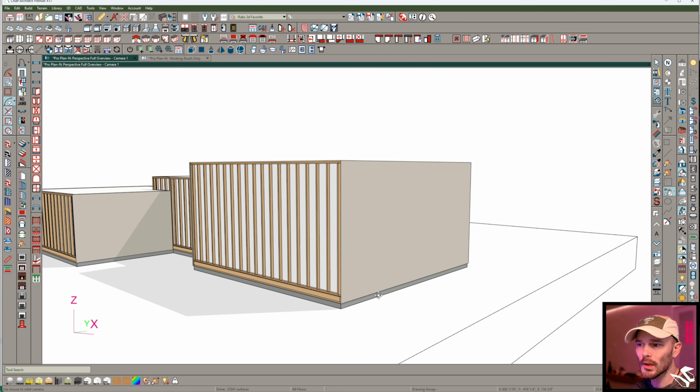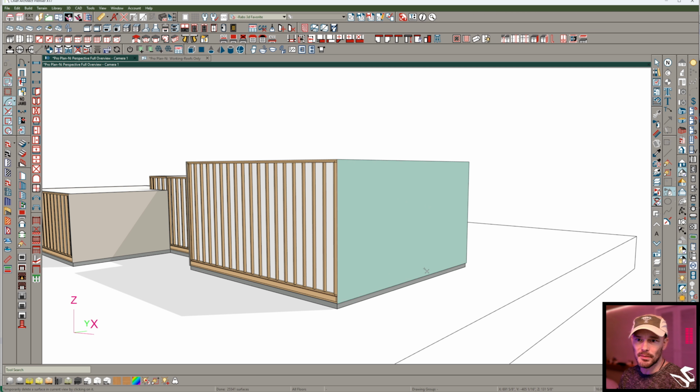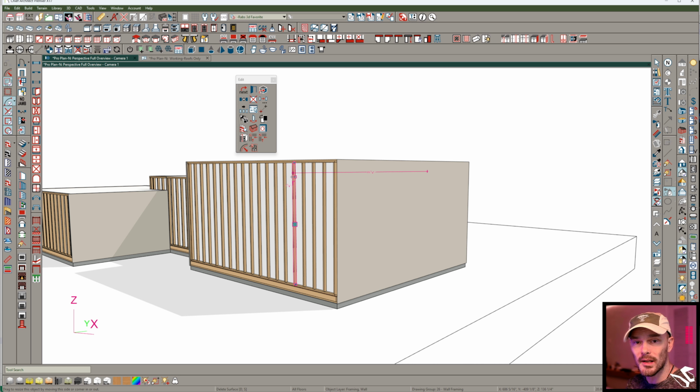Well, as a builder, I'm building the lower platform of this building, and once I have that, I'm standing on that platform. I've got my bags on, I've got my nails, nail gun, what have you, my 2x4s laid out with my chop saws, and I'm cutting these studs, all right? Or I'm getting pre-cut studs, because this is such a common approach that even the big box stores have studs cut to the correct length for this wall I have right here in Chief Architect, as well as this wall and this wall. I can go to my big box store right now and buy one of these framing members already cut to length, because that's how common this is, okay?